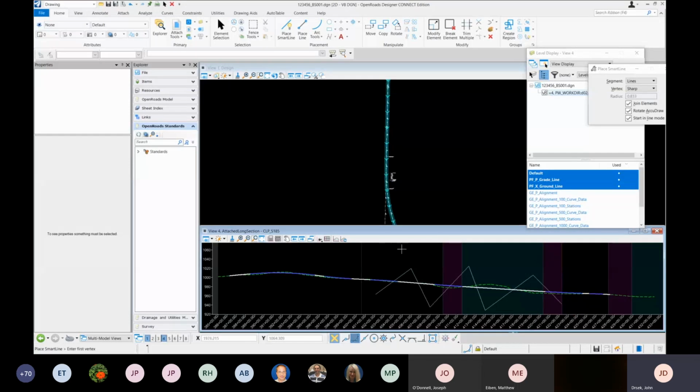All right. So I'm drawing it in the profile in my bridge base map. I'm not drawing it in my geometry file. So if I go back to my geometry file, I'm not going to see that, and I probably don't want to see that because maybe the roadway guys are going to reference that geometry file, and they don't want to see the bridge stuff. So maybe there are cases where I'm not going to be drawing in that geometry, but I'm going to draw on that profile just through a reference, like I'm doing here.